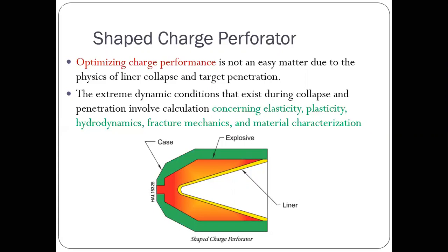Sir, in deep penetrating, the diameter of casing will be smaller than the diameter of the carrier, right? Yes, it looks similar, but if you consider big hole charges, then the diameter of the hole in the carrier, when it penetrates, is quite small as compared to the diameter it generates at the casing. It's not the diameter of the carrier. Basically, it is the diameter that is created when the jet is developed, meaning the perforating hole.